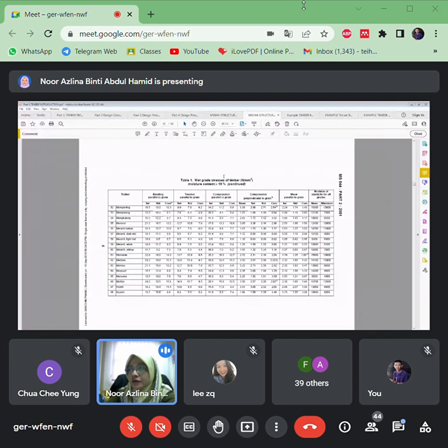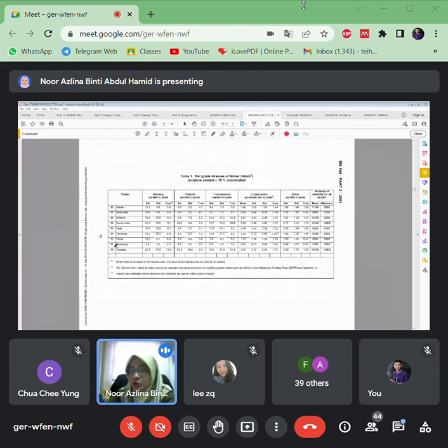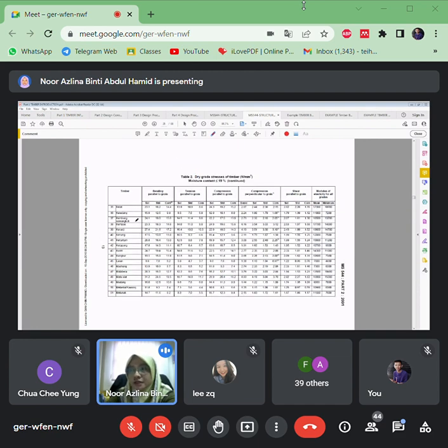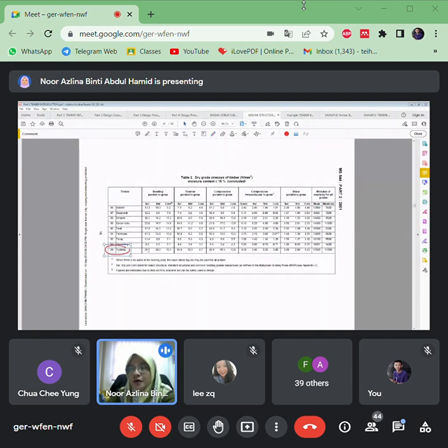Then we look at the other tables. If you look at this table 1, it keeps continuing until the last, which is tualang, about 94 species, that are considered in the design here. So all of these 94 species also have a dry timber, with moisture content less than 19%, which you can see in this table too. The species is repeated, but the values are for that timber in dry conditions, with moisture content equal to or less than 19%. So you can see the 94 species again, ending with tualang, but with values according to its dry conditions.